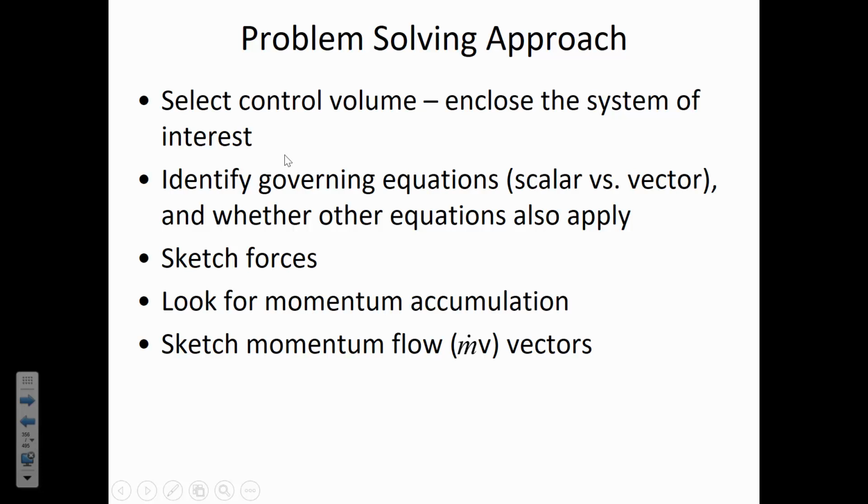So we could use Bernoulli's equation between location 1 and location 2 to find the jet velocity if we were pushing on this with some certain force. That's an example of a problem type where there may be multiple governing equations that apply in the same problem beyond just the momentum equation itself.